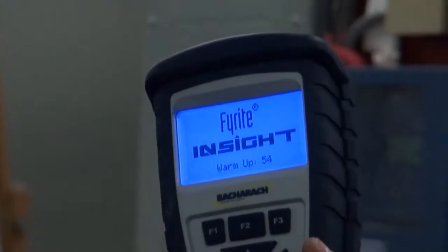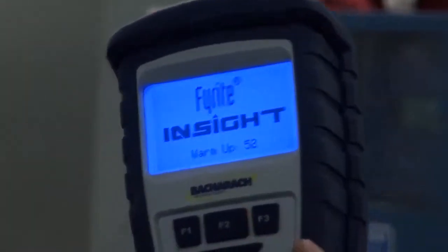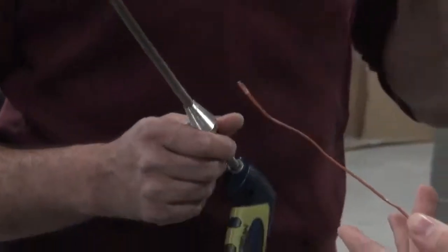You fire up the analyzer, it's going to go through a calibration process for about 60 seconds. What it's doing is it's actually turning the vacuum on and it's pulling air through the probe. It's calibrating its sensors. We should really be doing this outside in a well-ventilated space, just in case we have any carbon monoxide or carbon dioxide inside this room. We don't want this analyzer to make that reading the baseline.